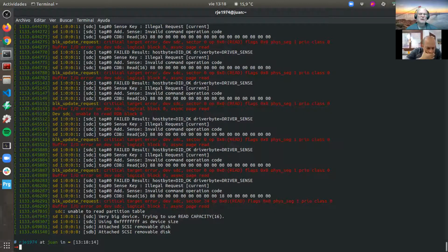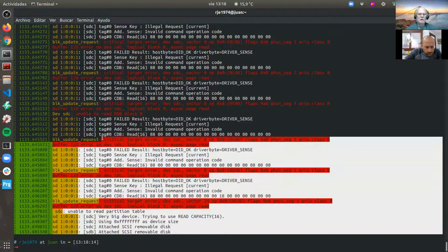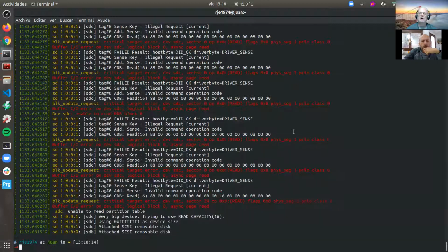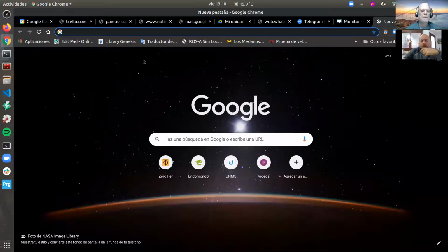So it looks to me like it didn't recognize the board, or it should have put some information out there. So I think that just the bare board is not going to talk to you. You have to have code to talk to that USB port. You have to have firmware that'll talk to that USB port. So probably like on the blue pill, you're gonna have to load something in for it to understand that. Yes.